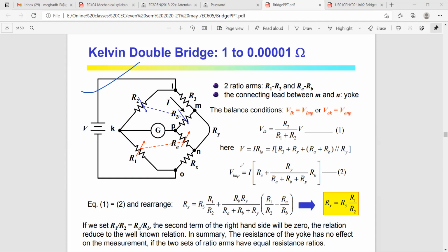That is important, where you can see the connection of the galvanometer between those two separate lines. Why we are opting for this connection is that it minimizes the effect of connecting leads and the unknown resistors, that is R, and definitely the S, which I have shown you in my previous diagram, and that can be easily found from here.